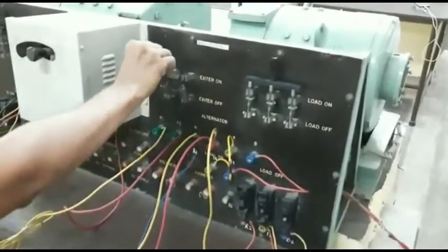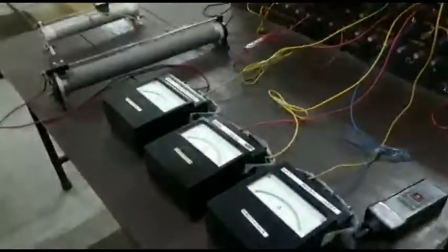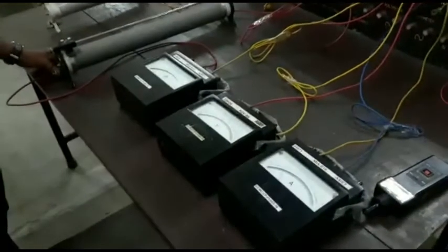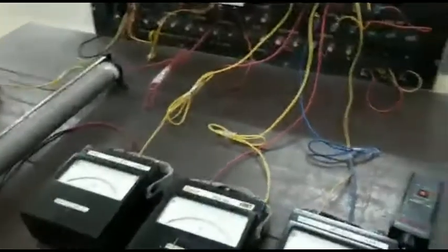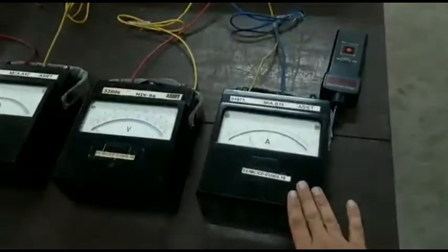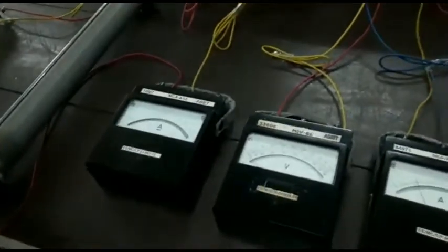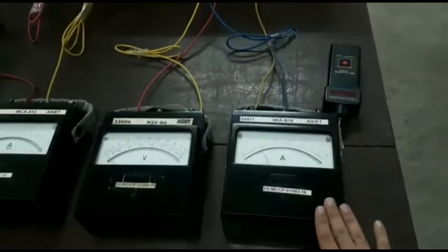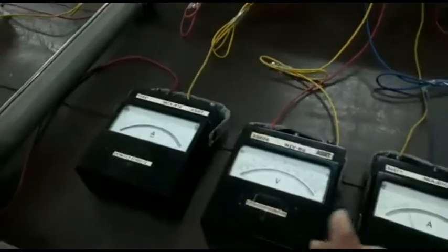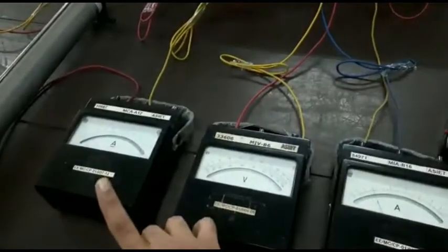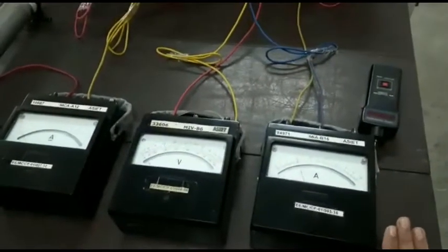The exciter should also be on, and for the short circuit test there is only a single reading. For a rated current of 7 ampere, you have to measure the value of the field current. For that you will read this ammeter. This is an AC ammeter, and this is the field current here. For obtaining an armature current of 7 ampere, which is the rated current of the generator, what is the value of the field current? Only a single reading has to be recorded. For a particular value of IF, you get 7 ampere in the armature. That you have to record, and that will end the short circuit test.